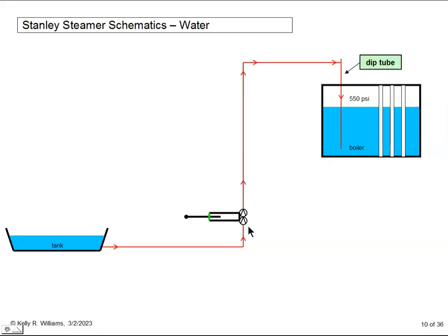And we send it to the boiler. The dip tube delivers the water near the bottom. Over time it gets plugged by rust and sediment. There is a cap here at the top so that it can be periodically drilled out.